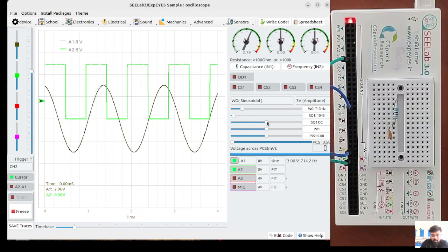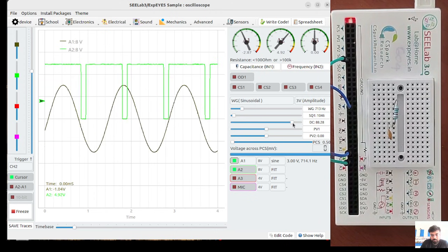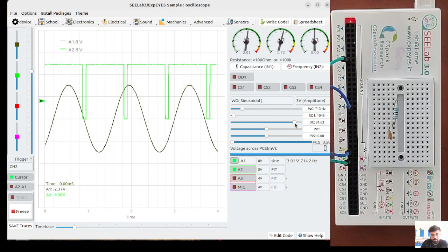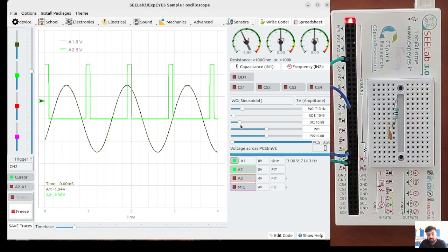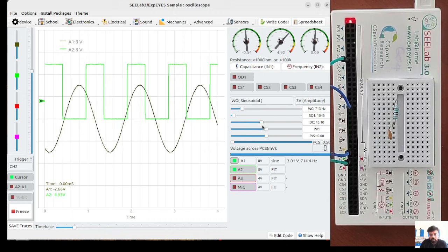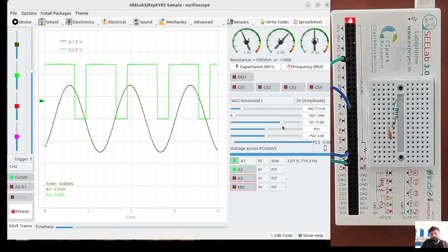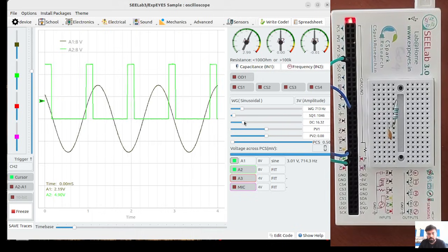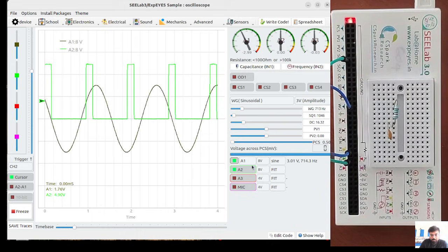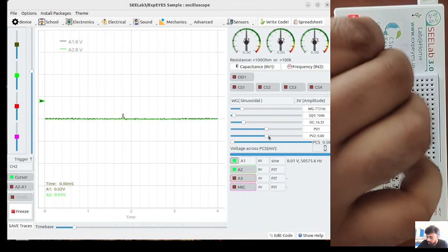You can also set the duty cycle for the square wave, which is the amount of time it spends on and the amount of time it spends off, the ratio. So I see 90% duty cycle looks like this and 10% looks like this. This is commonly used to adjust the intensity of LEDs. All your LED lightings usually do this flickering thing where you can't perceive the flickering, but you can see the net brightness, the average amount of current that flowed through the LED, resulting in the average amount of light. Now you have PV1 and PV2, which are voltage outputs.